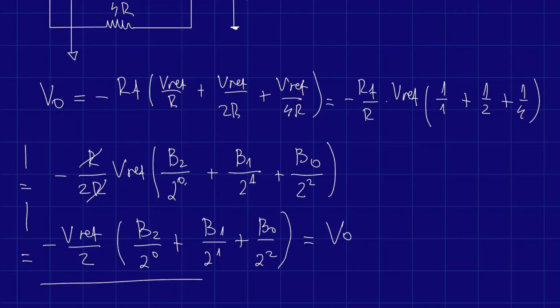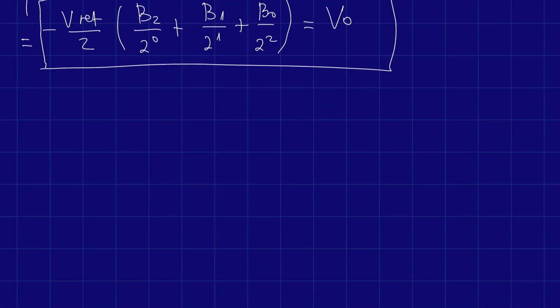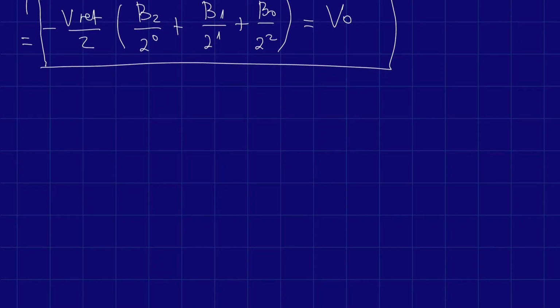Okay, so we've got one very important formula here, which basically means that we put our input in these 3 spaces right here. We put our 3 bits, and we have our reference voltage right here, and then we get some output after our conversion. Now let's look at an example, and while we're doing that, you'll also learn how to find the maximum representable voltage. So yeah, we want to represent our biggest number possible in this example, which with 3 bits would be just 111.